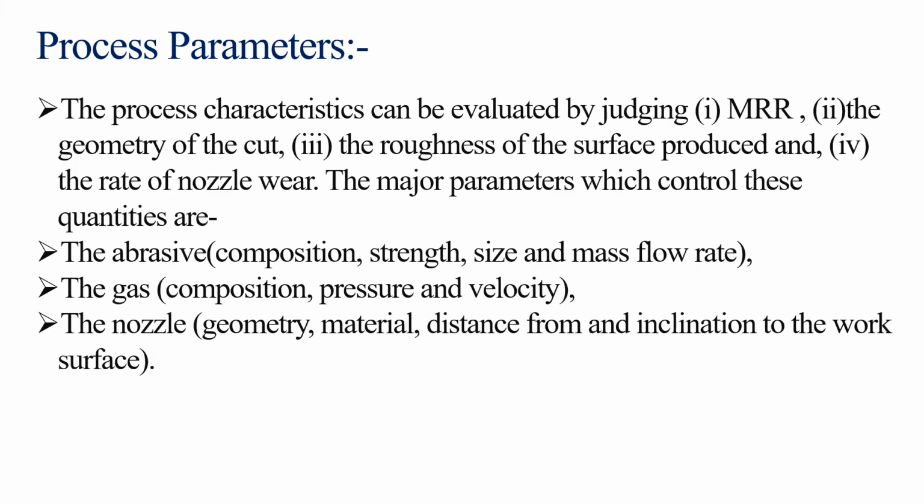Next, process parameters. The process can be evaluated by judging the material removal rate, the geometry of the cut, the roughness of the surface produced, and the rate of nozzle wear. The major parameters which control these quantities are the abrasive: composition, strength, size and mass flow rate; the gas: composition, pressure and velocity; and the nozzle: geometry, material, distance and inclination to the work surface.